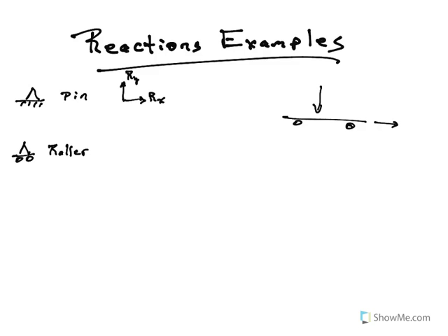However, if I stand on it, so I'm pushing down on the top of this bar, this skateboard, well, those wheels are on top of the ground, and obviously the skateboard doesn't fall through the ground, so there's a reaction by the supports, by the wheels, to push up. Now in physics we call that a normal force, but here it's just a reaction by the support, and so for rollers you always have the perpendicular reaction. Now, in the way I drew the roller, of course, the reaction is vertical, so I'd call it Ry.